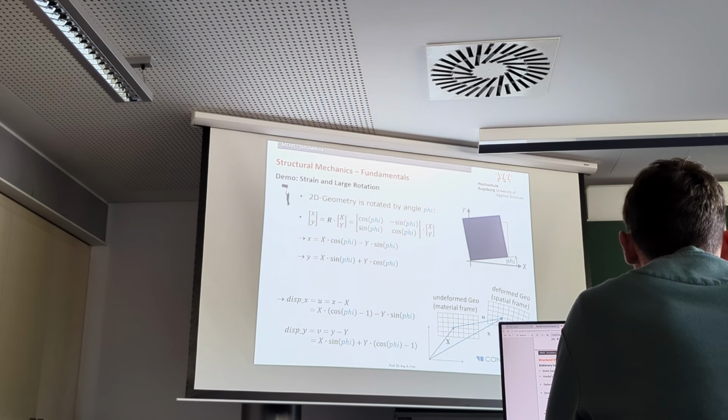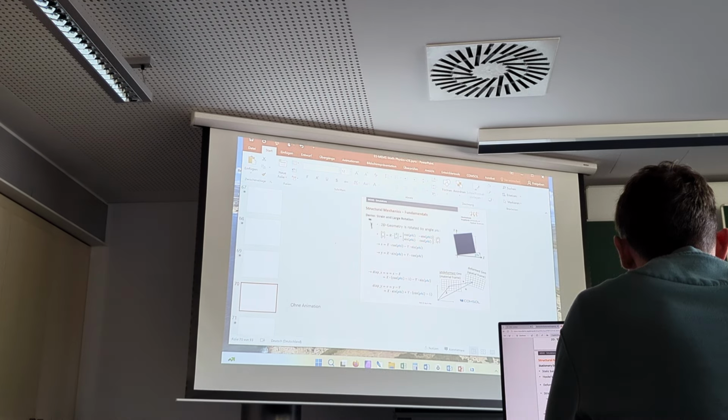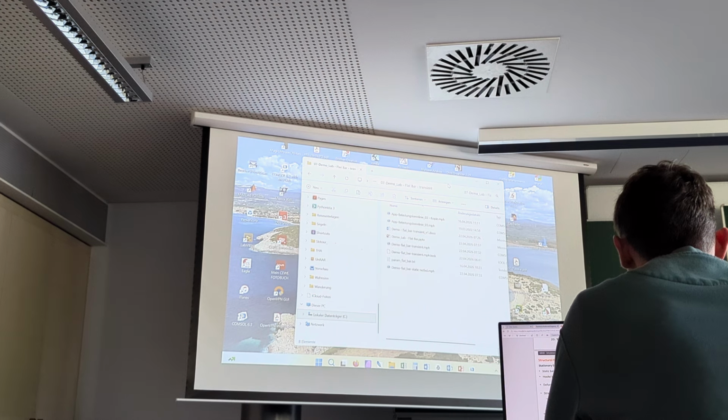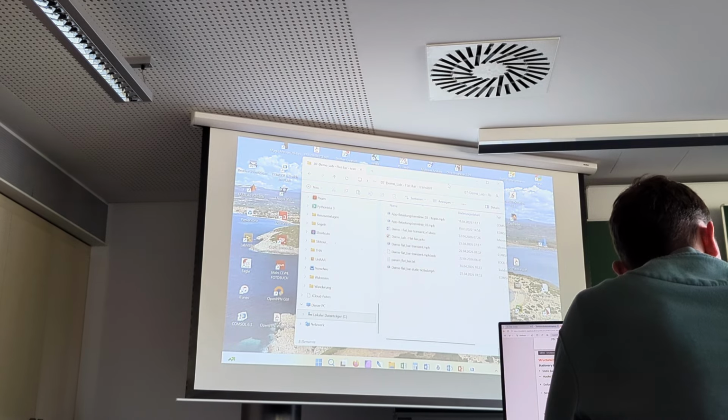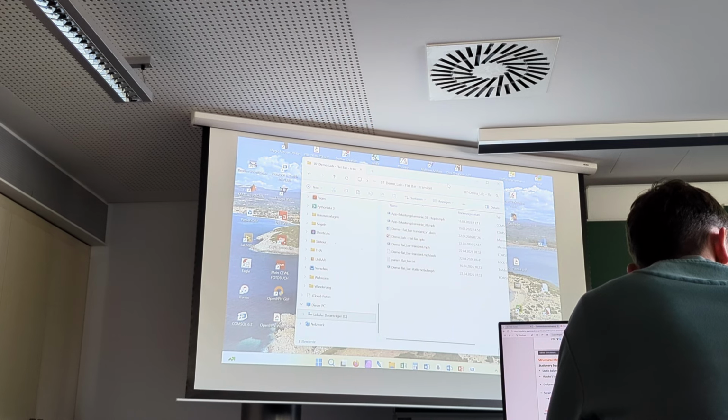Maybe it makes sense to appreciate the things we just discussed, to see it in real life in COMSOL. And what is the bottom line for all this? I tried to explain the background. What you technically have to do is kind of simple. You have to decide whether you put a mark for using geometric nonlinearity, it's just a mark, or if you want to make it numerically simpler, you need to know some adjustments. So that is very simple.